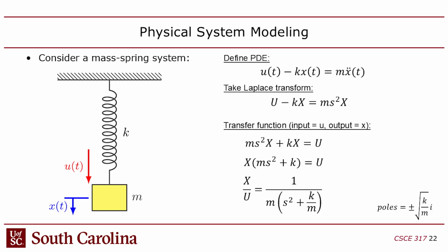So then you can convert this to Laplace. The spring constant is K in this case. That's just how stiff, the stiffness. K is stiffness. And then you can create the transfer function for that, right? Does that make sense? So it turns out, is this stable or unstable?